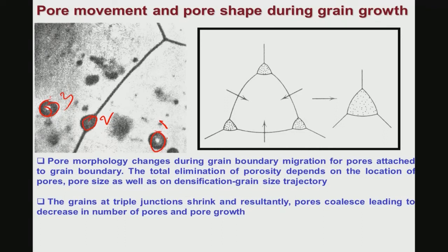Pore number 2 is located at the grain boundary region. The pores located at the grain boundary can be removed very easily, simply because the grain boundary diffusion process is much faster than the lattice diffusion process. The pores marked number 1 and number 3 will be very difficult to remove, simply because the bulk diffusion process is extremely slow.